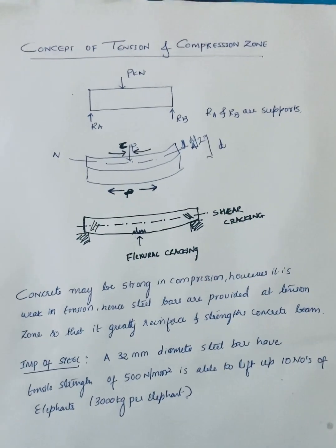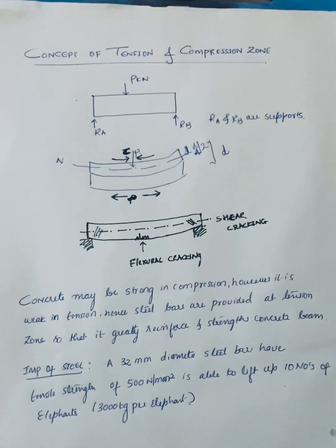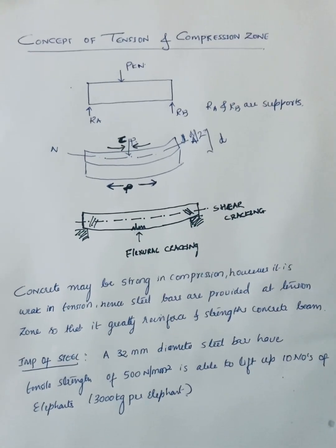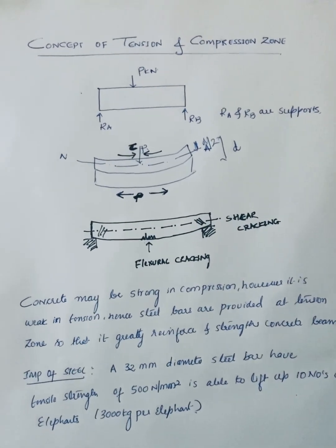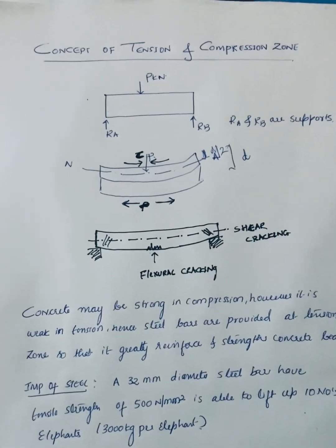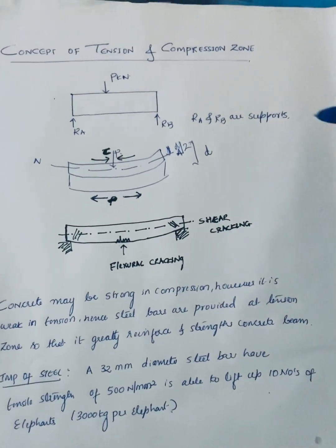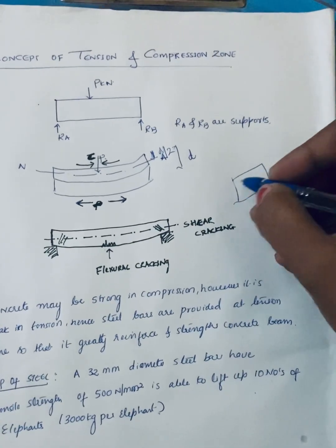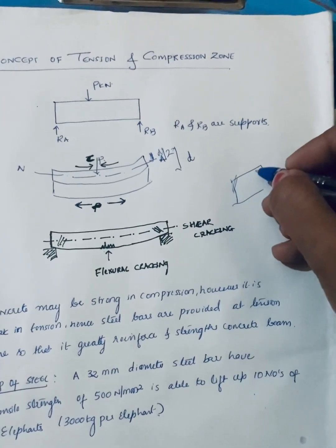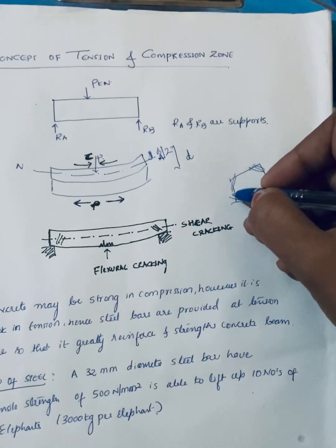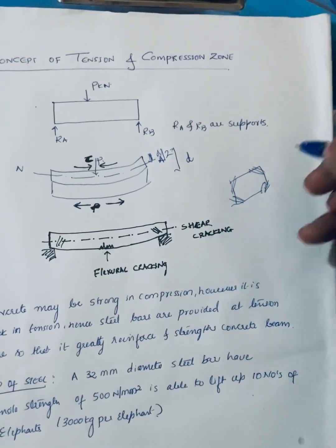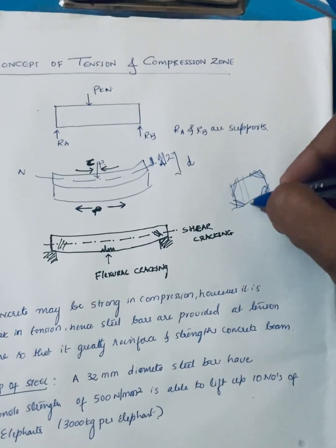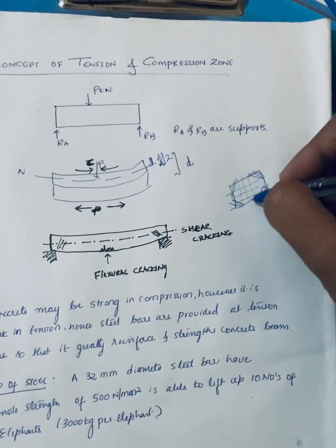For example, at a live construction site, we can observe that at the corners of a slab there is more steel provided, whereas at the center the provision of steel is less.